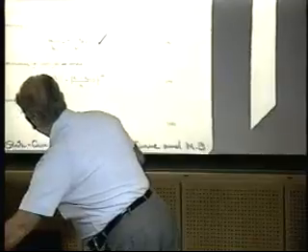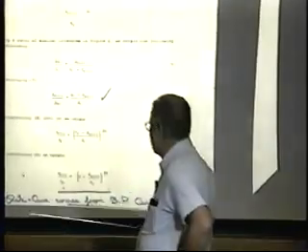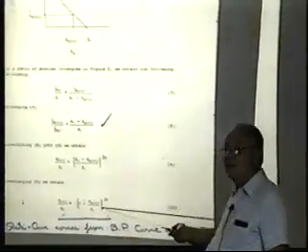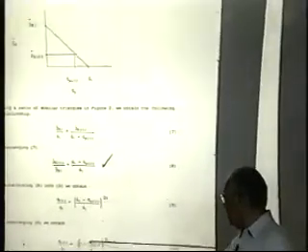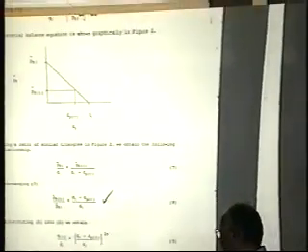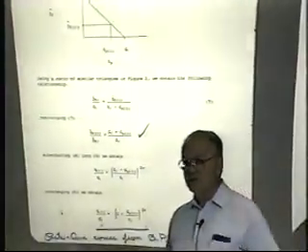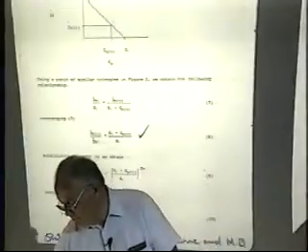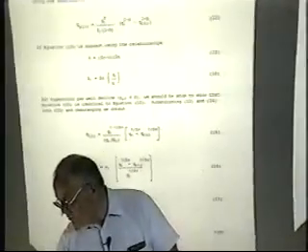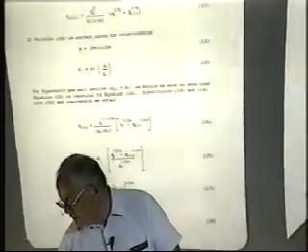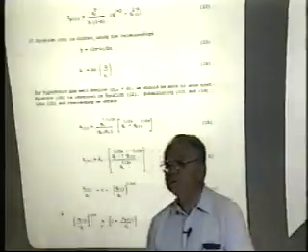You end up with the material balance equation, and you end up with exactly the same form that you saw earlier, from a completely different approach. Or the rate cum comes from the back pressure curve and the material balance. That's where it comes from. And again, you can see this on gas. You'd never get there if you tried to do these derivations on oil, because you're dealing with relative permeability.